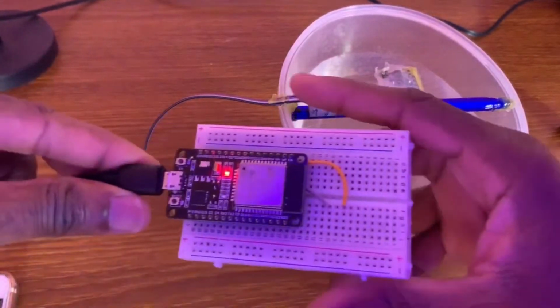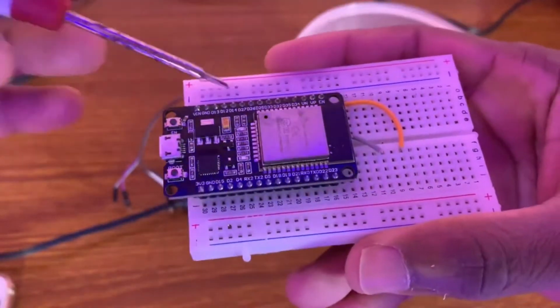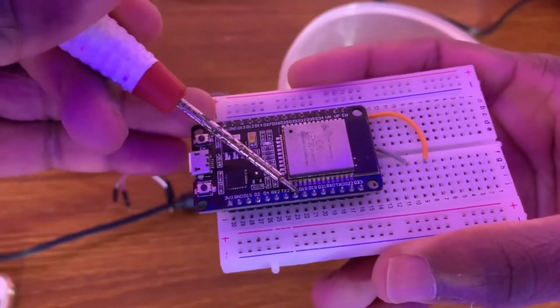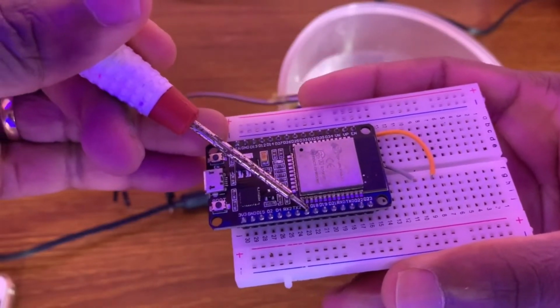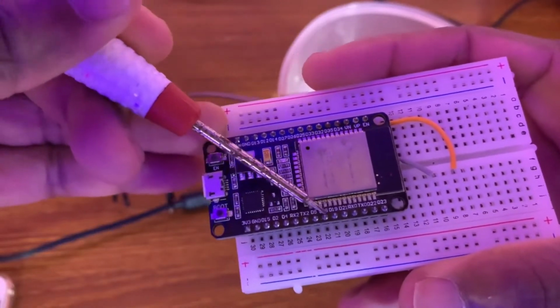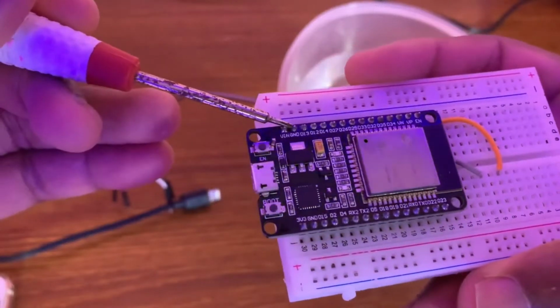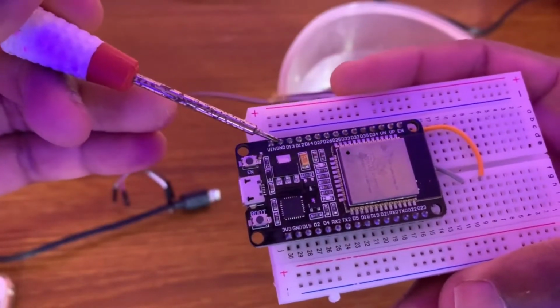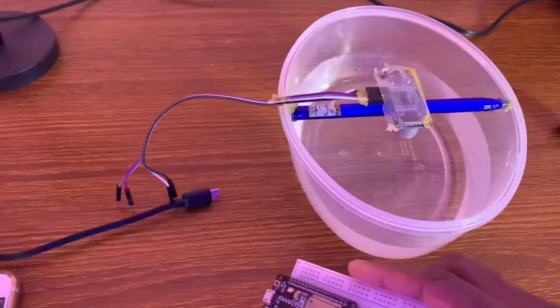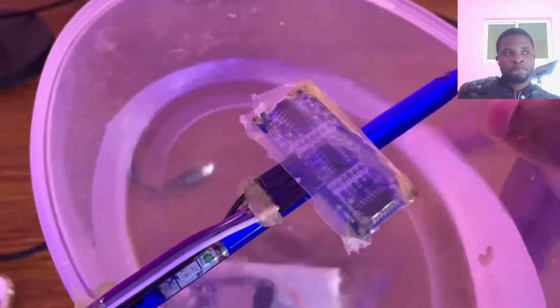Okay, I need the ESP32 board, and GPIO 5 is attached to the trigger pin, and the echo pin to GPIO 15. So the VCC to the V in, and the ground of the sensor to ground. So that's the sensor. The ultrasonic sensor has 4 pins,